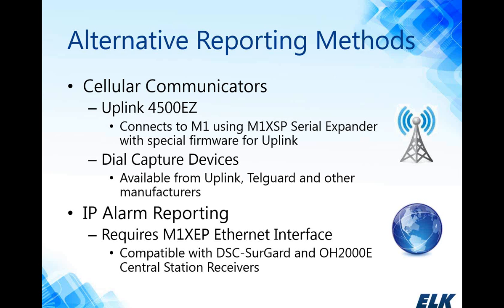On the market today, there are a number of dial capture devices from companies such as Uplink and Telguard and others, which simulate phone line voltage and current so that the security system doesn't know it's not connected to a landline. And when the system goes into alarm, these devices will capture that data and then relay it through their network to your central monitoring station.